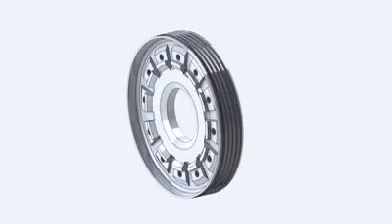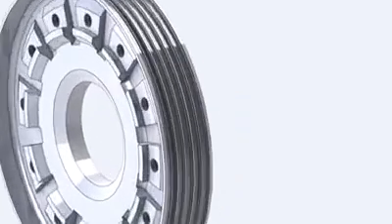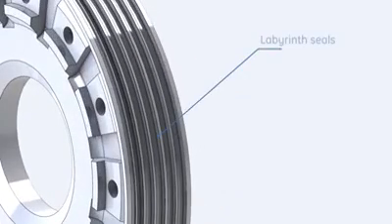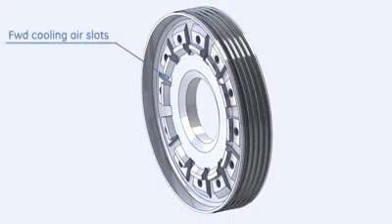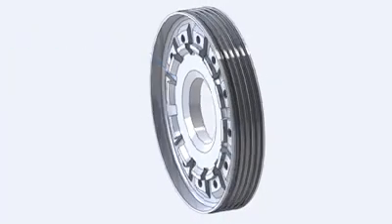The first wheel spacer is located between the first and second turbine wheels. The spacer's function is to define the axial position of the turbine wheels. The outer diameter of the spacer carries the diaphragm sealing lands. Slots are machined on both forward and aft faces for cooling functions.